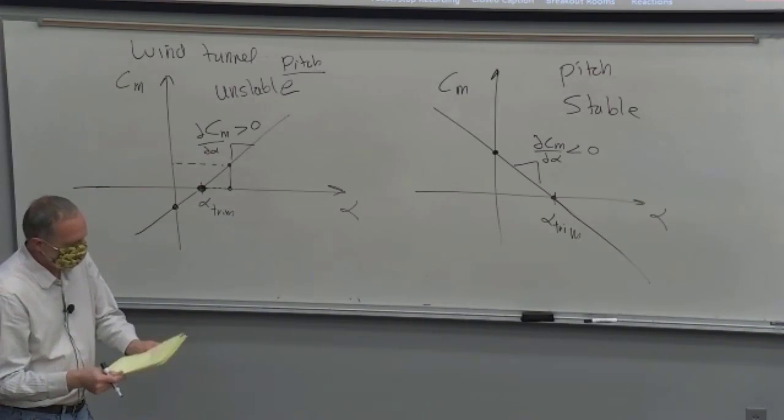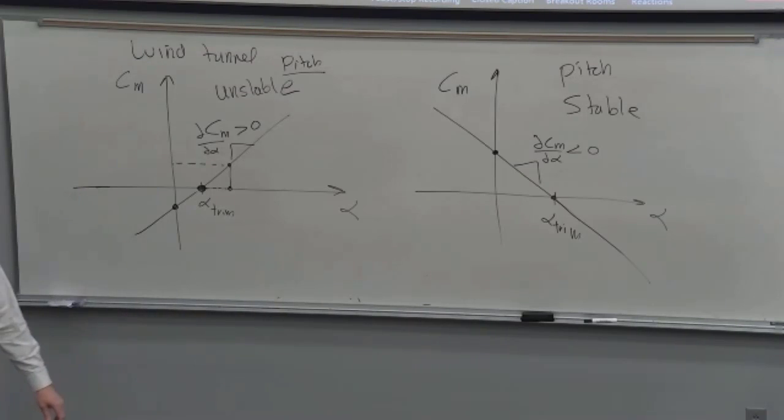So hopefully you learn more than this from this class, but if you only remember 2 things, when you go to build your airplane, first off, make sure you can trim it in pitch. And second, make sure that you have pitch stability on the airplane.